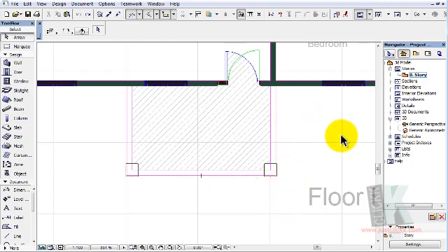And remember that we just opened this AutoCAD file in ArchiCAD, so the stories are not created automatically, but we can create them. By default, ArchiCAD creates a ground floor, first floor, and second floor automatically, but it didn't do that here because we opened this directly as an AutoCAD file. We can go ahead and create stories in order to access the story that is handling this suspended wall here. Mind you, ArchiCAD by default creates stories at a height of 3,100.